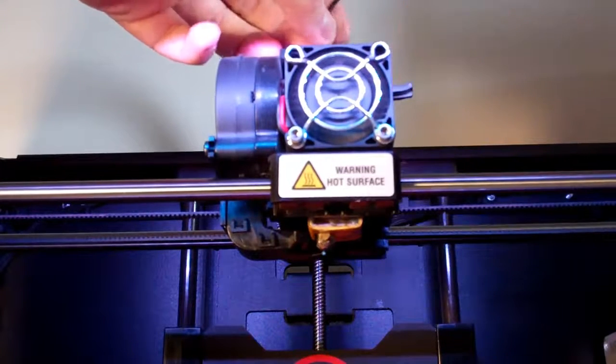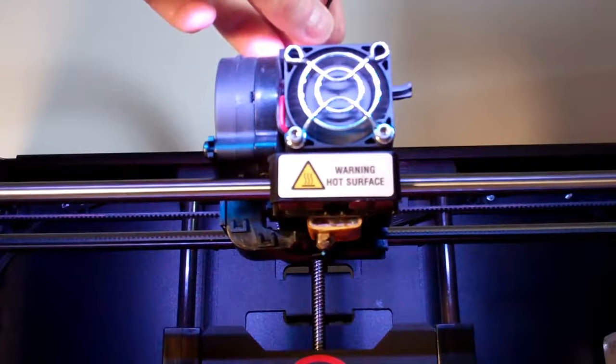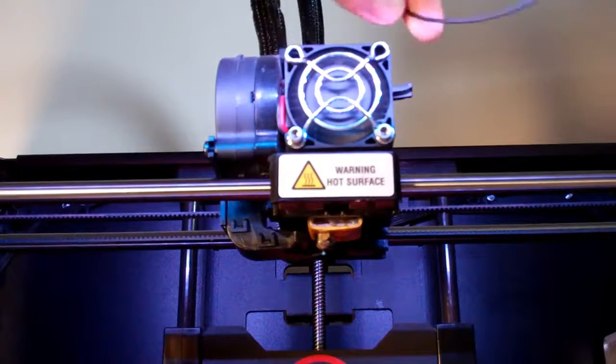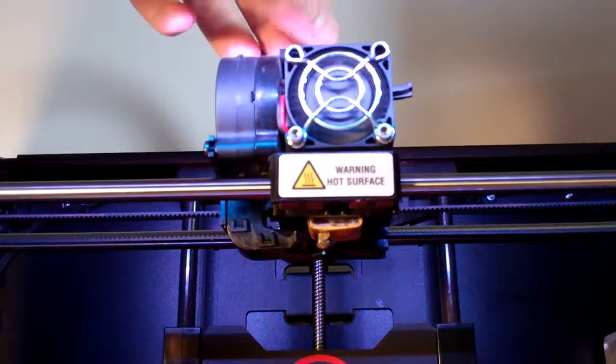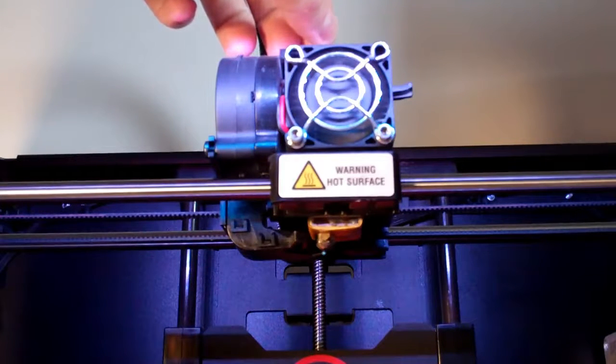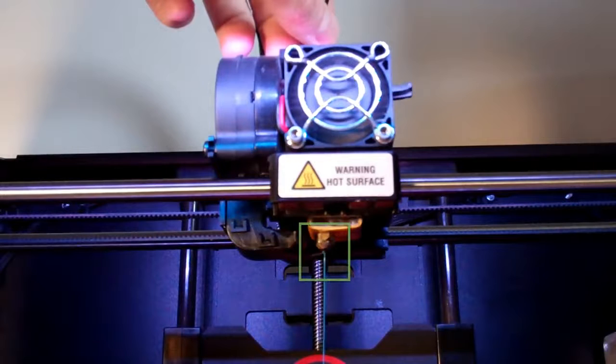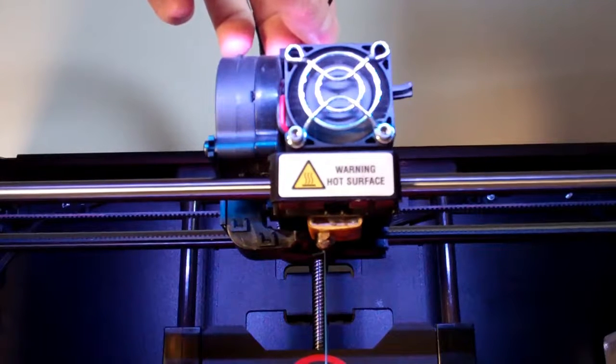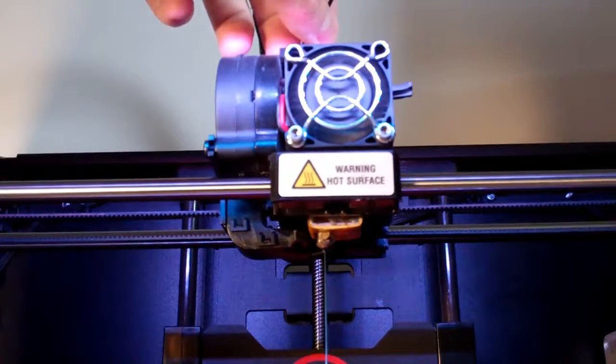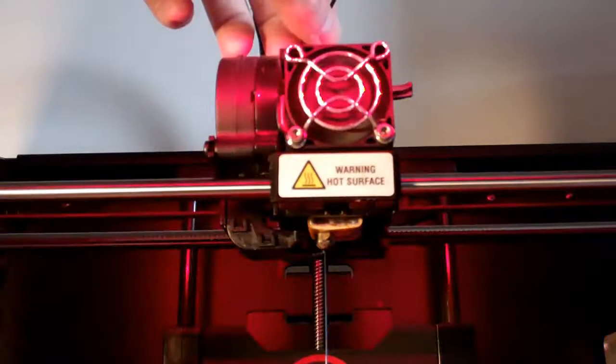And I'm going to have to press the lever down because it's a flexible filament, it won't be able to push in by itself. So push that little lever to help it in there. So you're gonna see that extrude at the bottom. That's extruding the blue PLA plastic that's already in the nozzle. So the goal is to get rid of the PLA plastic that's already in there, and hopefully we'll see some ninjaflex come out in a second. But we are going to have to repeat this process a couple of times.